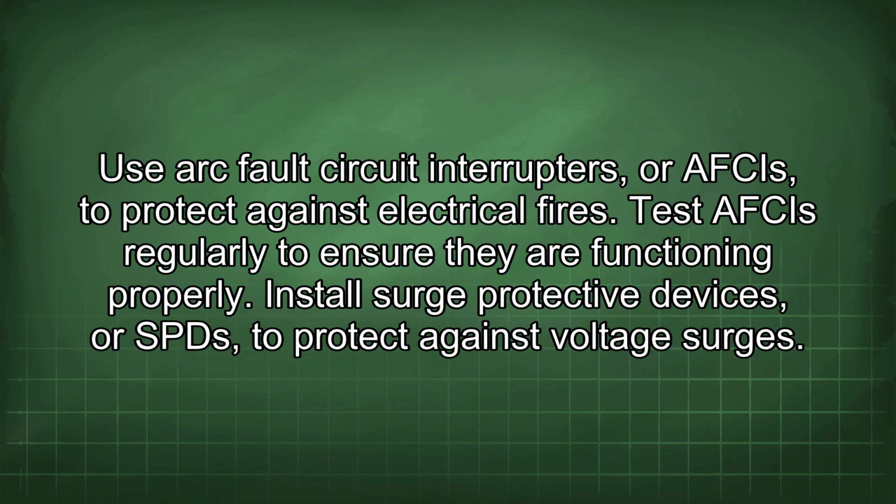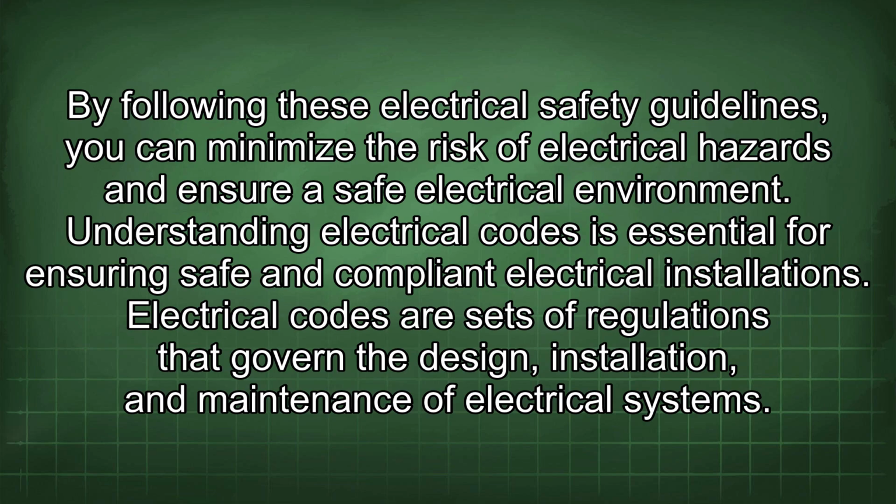Use arc fault circuit interrupters, or AFCIs, to protect against electrical fires. Test AFCIs regularly to ensure they are functioning properly. Install surge protective devices, or SPDs, to protect against voltage surges. By following these electrical safety guidelines, you can minimize the risk of electrical hazards and ensure a safe electrical environment.